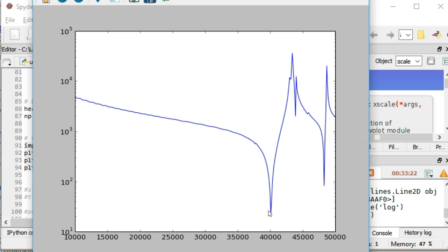Here we have a mechanical resonance, which occurs almost exactly at 40 kilohertz, and then it rises after that, and it decreases again here at another resonance, which is not the operating frequency. Typically when you're designing transducers, you design them such that these resonances, which aren't the main resonance of the system, meaning the lowest impedance point, are far away.